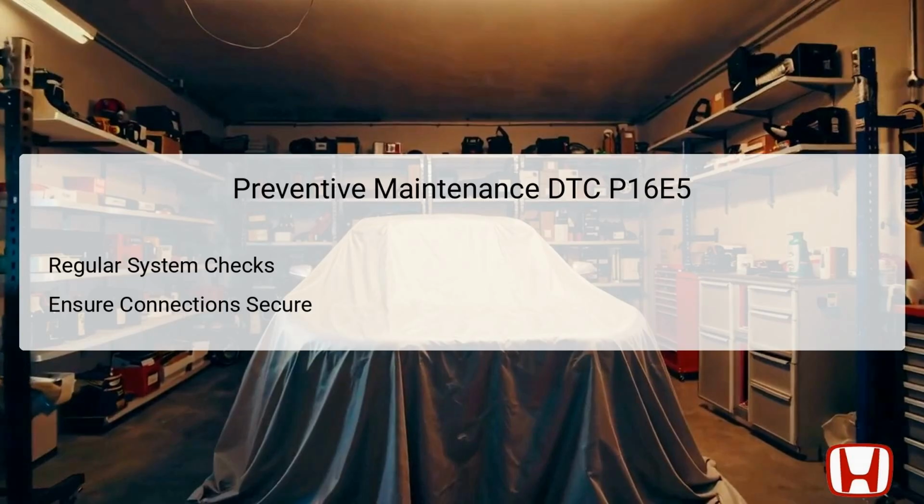It is advisable to make sure all connections, including those of the PCM and DC-DC converter, remain secure and free of corrosion. Additionally, routine inspections of the vehicle's battery and related electronic systems can preemptively identify potential failures before they escalate into significant problems. By investing time in preventive measures, car owners can help sustain vehicle performance and reliability.